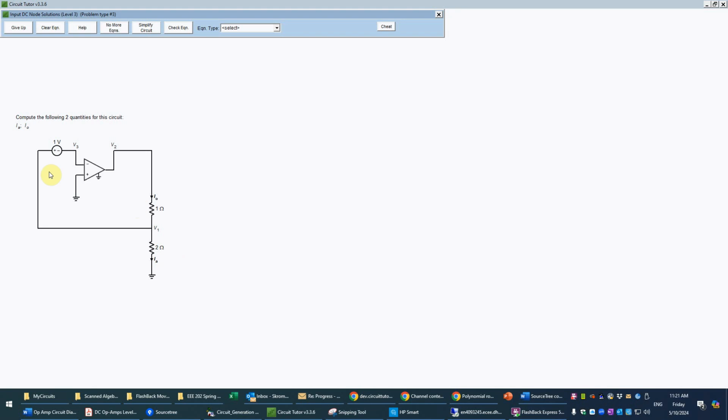But basically what this is doing is it's taking an input voltage, and then the output current here is actually IA. This does not have an output voltage really, and so it's converting voltage to a current. This is called a transimpedance amplifier. So in any case, we can go ahead and solve this by standard methods. You could actually solve it by inspection, which maybe I'll talk about a little bit at the end, but let's just go ahead and do the straightforward method.